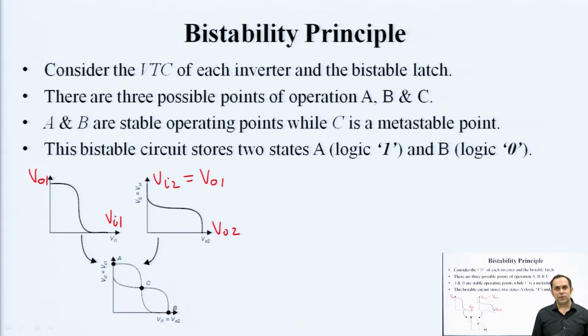Another benefit of rotation is that when you combine these two graphs, the resultant graph is very easy to understand. So, this plus this is equal to this. You have added these two graphs and plotted them on the same single graph, in 2 dimensions. Then the graph looks something like this. This is the voltage transfer characteristic of your bistable latch circuit.